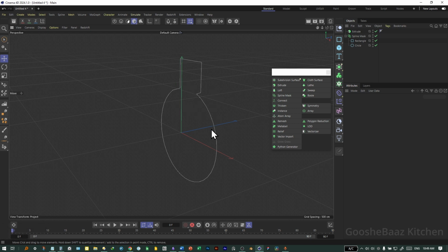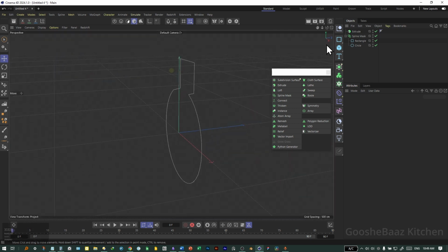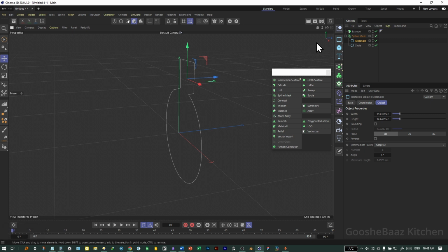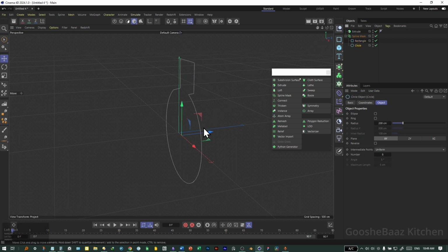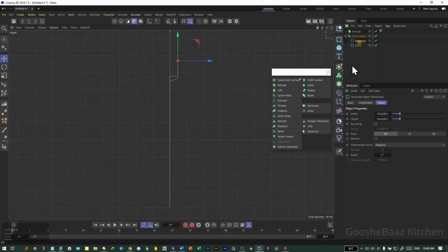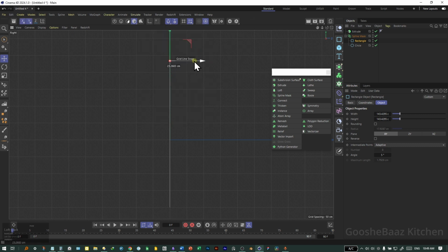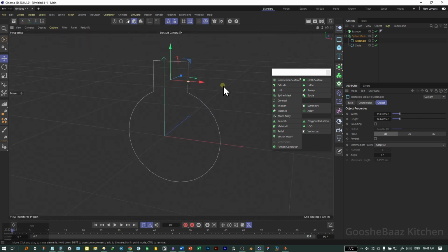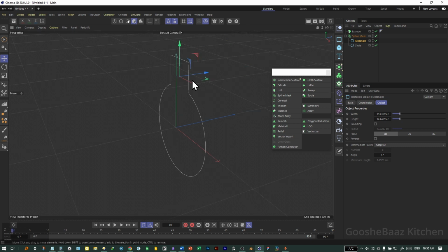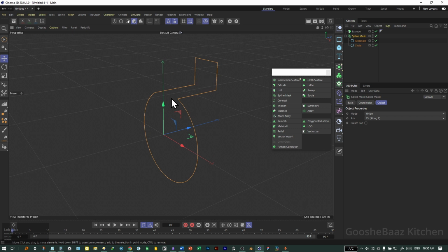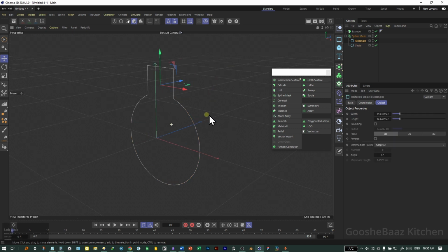the same plane. As you can see here, the rectangle is offset to the positive z-axis a little bit and the circle is not. So I grab this rectangle, come here, enable a snapping tool, click on the gear icon and select something like a grid work plane here. And I snap them both on the same plane. As you can see, if I drag the rectangle and offset it from the plane of the circle, there is something like a bug here. So make sure to always keep the splines on the same plane.